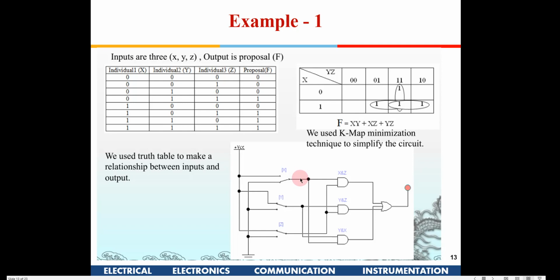So if you see here on this particular wire, there are only two possible voltages available: one is VCC, the other is ground. There is no hanging. If you use the common switches which are there in our homes, then there will be an error in the circuit, because the common switch is just a make and break switch, known as a single pole single throw switch. This is a single pole double throw switch. That means when you put it into the off position also, 1 volt is available at the output here and ground is available here. Is this clear? Why are we using these kinds of switches? Yeah, Kishan, is it okay?